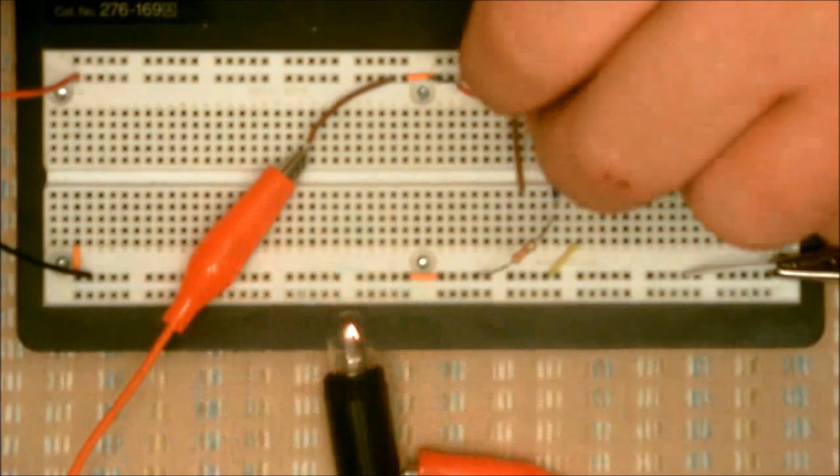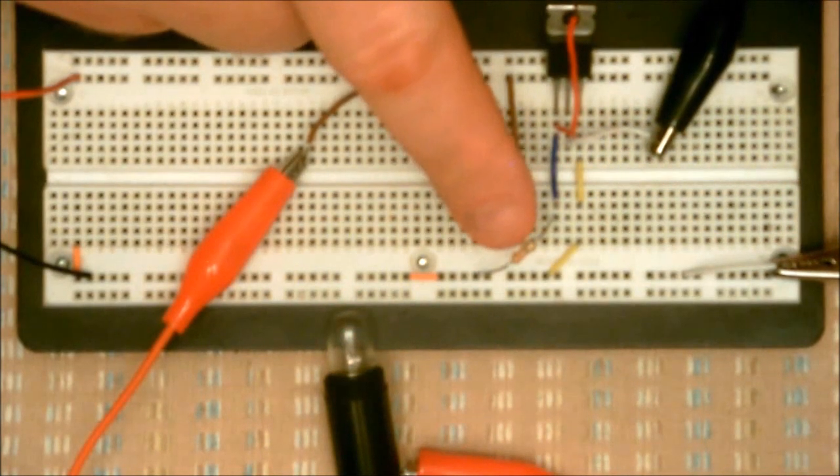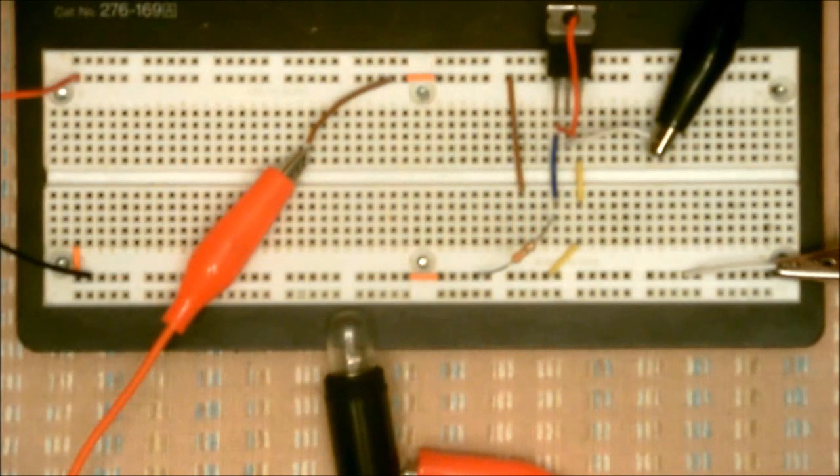But as soon as you remove it, this resistor discharges the charge out of the gate, forcing the gate to turn back off, or turning the transistor back off. This is what the resistors are used for. They only dissipate the charge that's built up in the transistor, so the transistor can turn off.